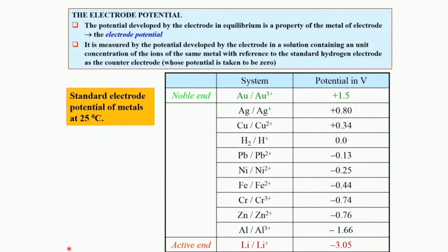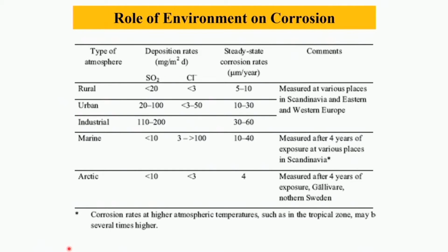This is typically an ideal series which gives you approximate information about the relative corrosiveness of different metallic materials in the standard solution and, naturally, under ideal conditions, that is at 25 degrees Celsius temperature and normal pressure. But you will find that the actual corrosion rate varies and depends on the kind of environment you are exposing and what the material composition actually is.